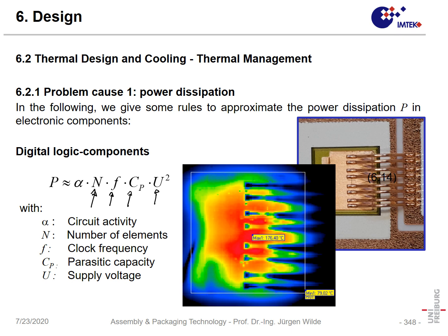And in that way, we could see that a microcontroller built in the technology of the year 1980 would dissipate tens or hundreds of kilowatt. And that, of course, is not tolerable. So the decrease of the voltage, the decrease of the capacitance, and of course also that circuit activity factor.